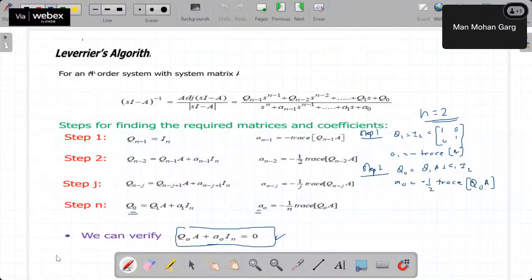The reason is that when we are designing a controller, we assume that whatever model we have obtained is the actual system. And this model is obtained based upon linear approximations, or perturbations around the DC operating point. Now, if the DC operating point itself varies a lot due to some reason, then this controller may not work properly. That's the reason. So the model should be as accurate as possible to the real system.